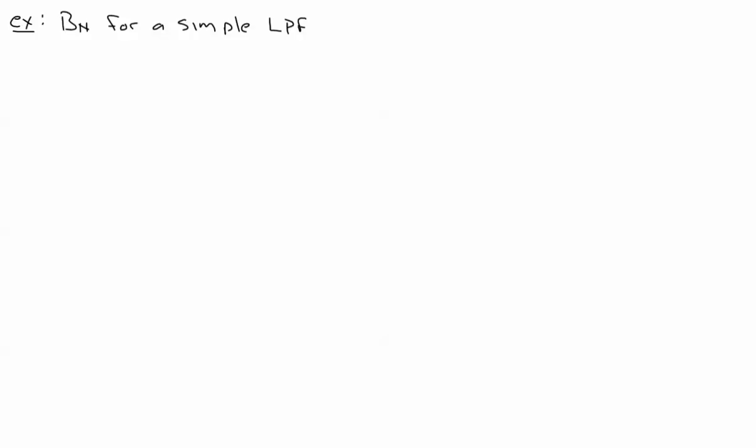My transfer function is going to look something like this. It's going to be A over 1 plus j 2 pi B f, where clearly H0 equals A.